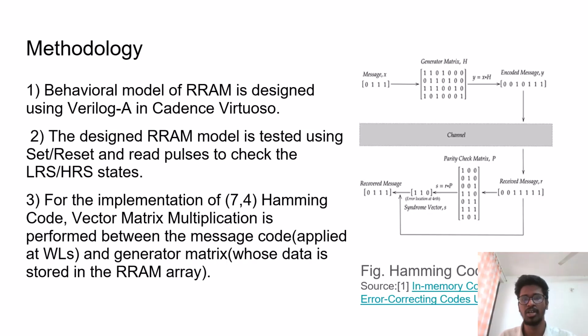Here we design a behavioral model of an RRAM using Verilog-A and the Cadence Virtuoso tool. This model captures the switching behavior of memory devices. After that, we tested the RRAM design by performing set and reset operations followed by a read operation. This helps in proper switching between the low resistance state and the high resistance state.